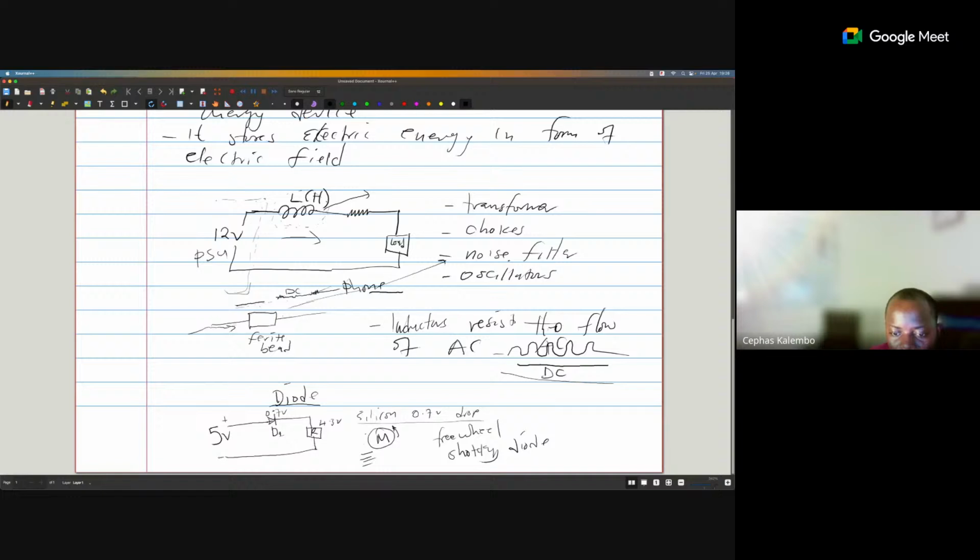So you'll have that diode there, then another diode there, and another, like that. When this motor comes to a stop, remember, there is a bit of accumulated or residue power that will remain in it, in the form of voltage or whatever that is.